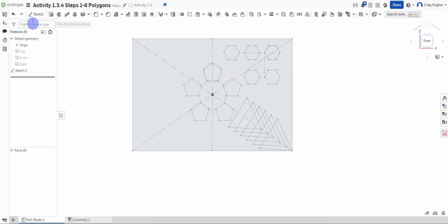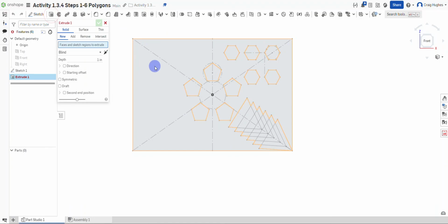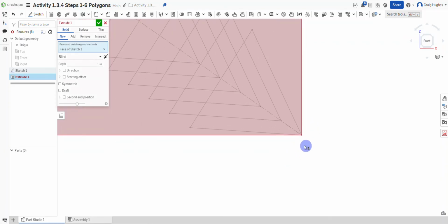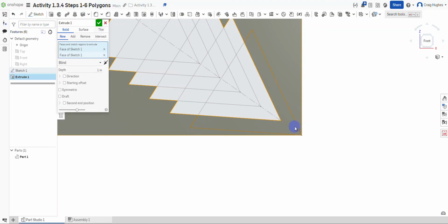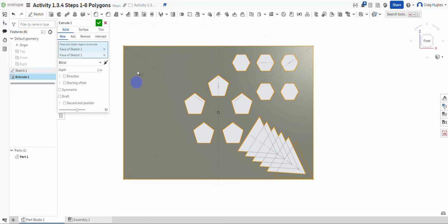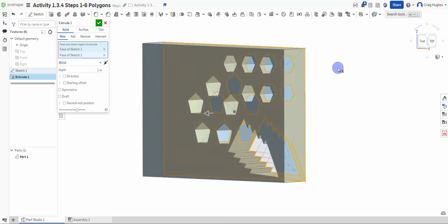And let's go ahead and extrude. I'm going to pick this large portion where there's no plate. You're going to get a red outline because right now it's not generating a solid, and it's probably because of this one right here. If I click on this corner, right where this is going, you're going to see that it now fills that portion in and gives us an actual solid.